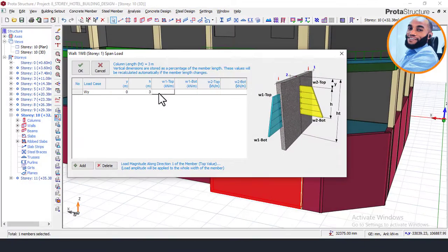So in that course, also on BS 8002 and EN 1991 Part 2 UK Annex, when it comes to vehicular load, knowing that vehicular loading has two classes, they have HA load and HB load.